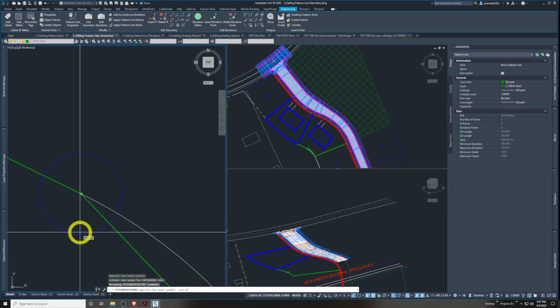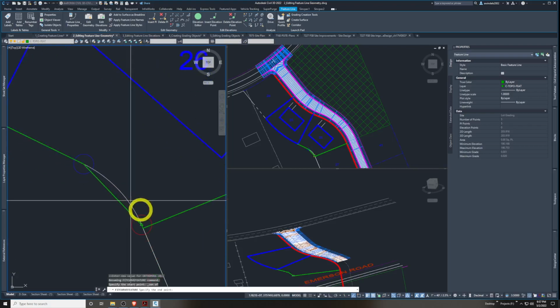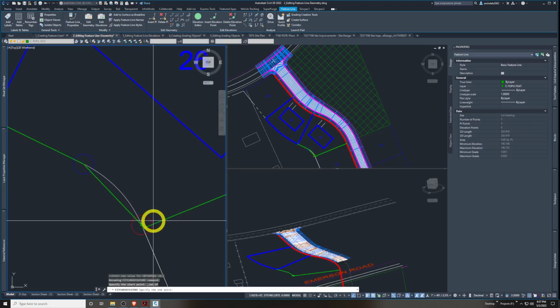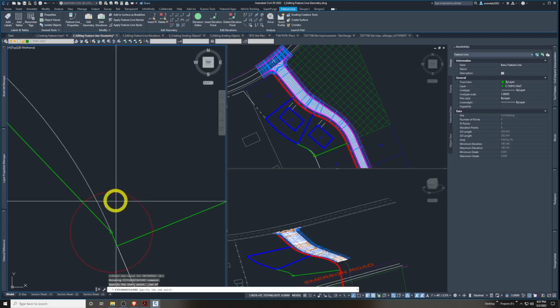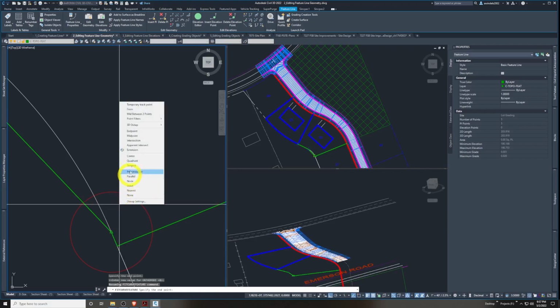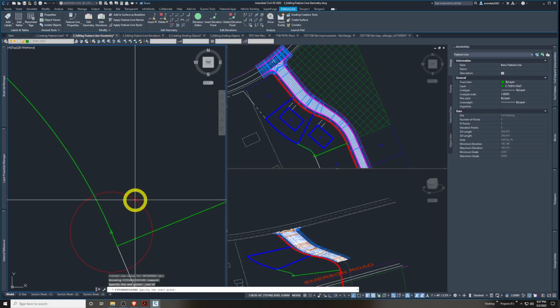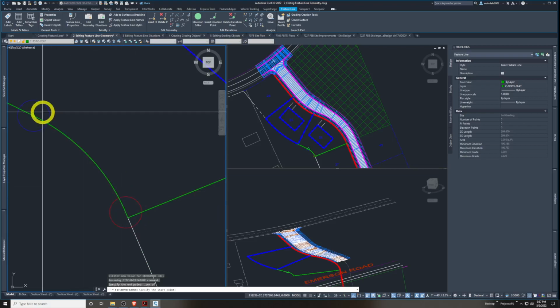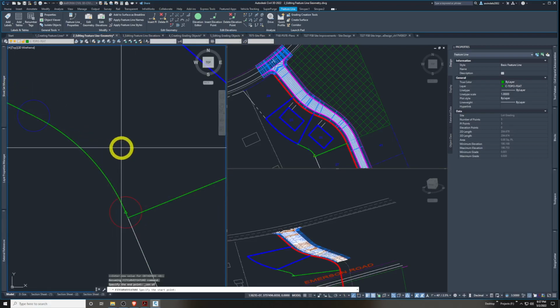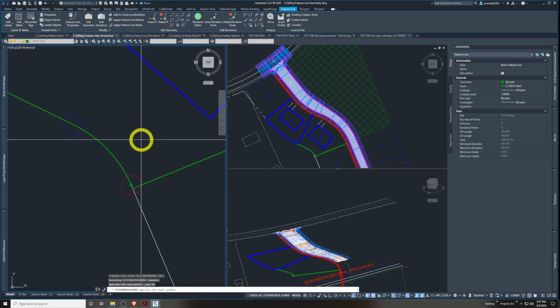There you go. And it wants to pick the endpoint. And use the center snap to hover to the center of, let's hold shift, right click again, center for one operation. There we go. You got to be very surgical on picking the centers of both of these. It fit the curve between these two exact points. That was good.